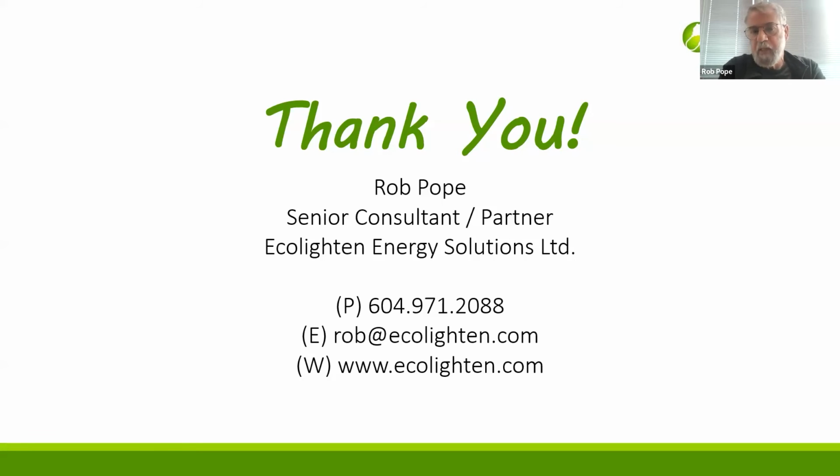Commissioning is pretty big. It also provides a baseline for future maintenance and repair. So the technician a few years later comes, sees the commissioning reports and says, okay, this is where the baseline was. Now let's check and see what's changed. So yeah, I'm glad you brought that up. Commissioning, I think eventually, is one step at a time. Right now we're working on load calculations, getting that into the authorities having jurisdiction, so that it's required in every jurisdiction, and that is going to come one way or another very soon.